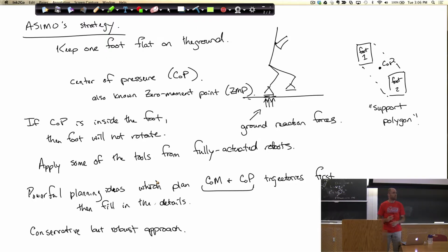Cool, yeah. What makes it fully actuated when we bolt one foot? So let's just count. If my foot was bolted to the ground here and I have a motor at every joint, I literally have an actuator on every joint, except for the ones that would connect me to the world. If I assume that this is fixed to the world, then by just counting up, I have the same number of actuators as degrees of freedom.